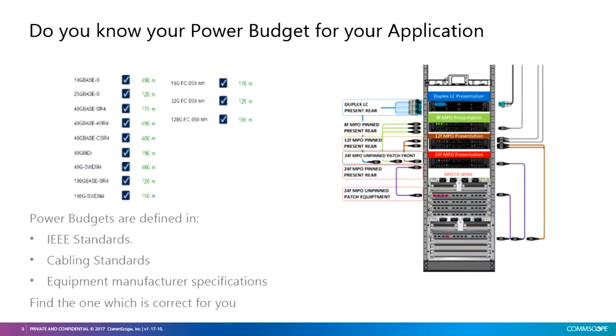The customer said, Murthy, if you put OM4 or OM5, it will be sufficient because it can support up to 550 meters. In CommScope by standard, it's around 450 meters. So we said, okay customer, you want to put OM4 or OM5, that's good, but I'll be very cautious before going with OM4 or OM5 in the data center.